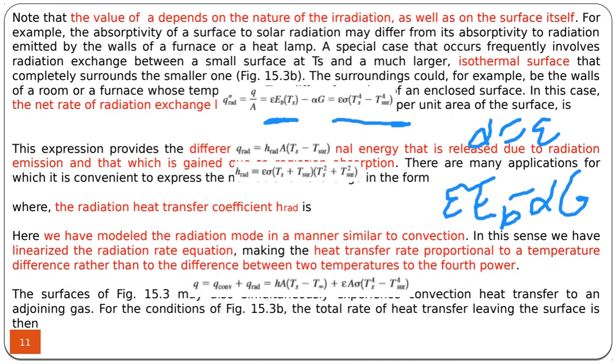So there is a heat loss from, let's say, 0 degrees or 1 degrees on the grass to a temperature which is at minus 70 degrees. You need to convert them to Kelvin anyway. So the amount of heat loss from the grass to the space, to the atmosphere during the night is this much. And this heat loss will cause the surface temperature to go down. If it goes down below zero, it will freeze.